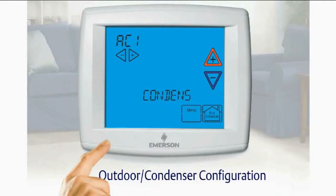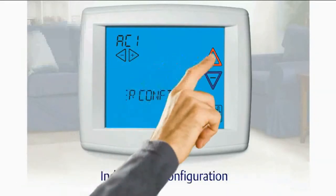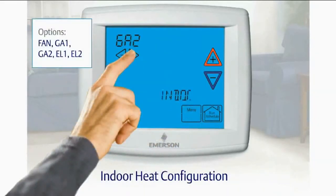Menu item 1, outdoor and condenser configuration. This unit can be configured for a single stage or multi-stage air conditioner, single stage or multi-stage heat pump, or no air conditioning. Item number 2, indoor heat configuration.